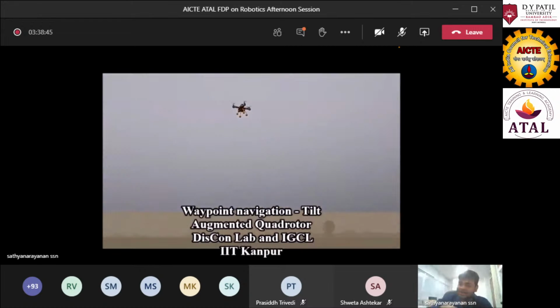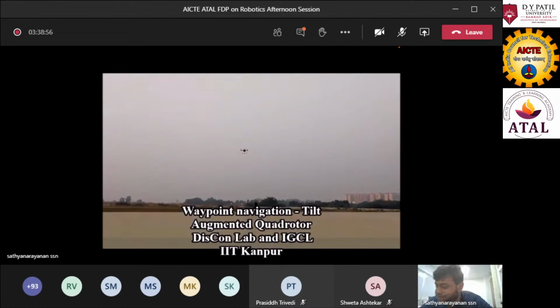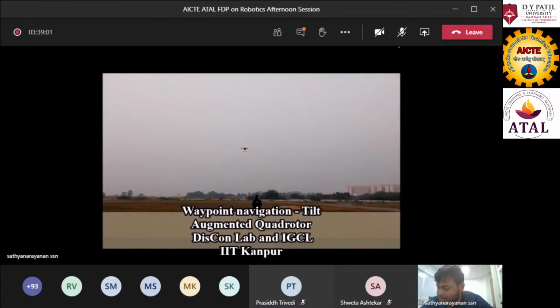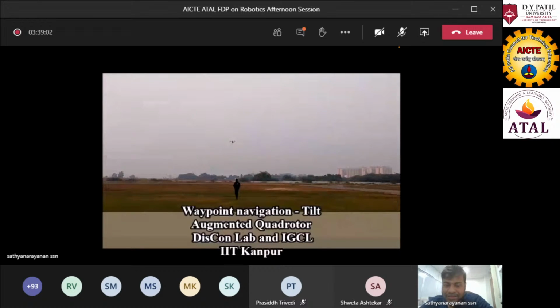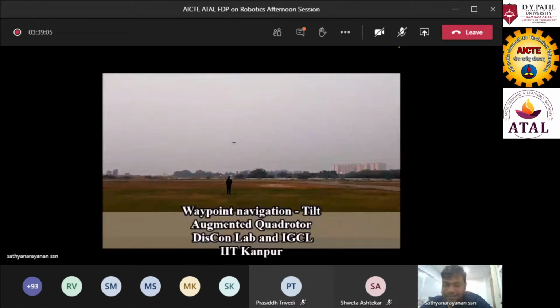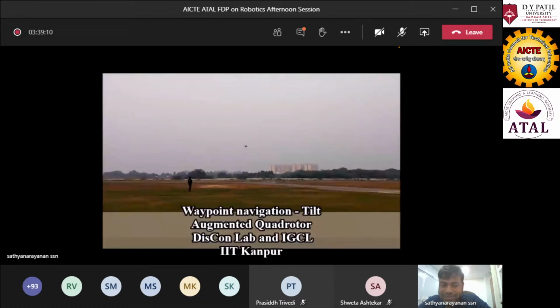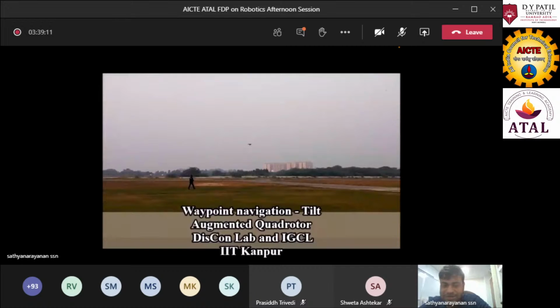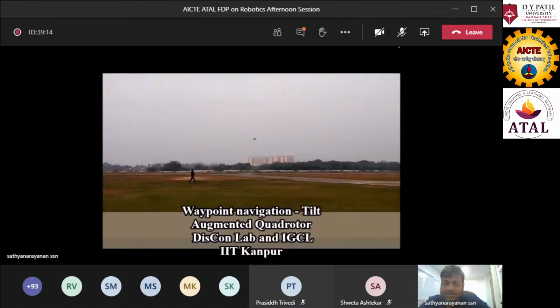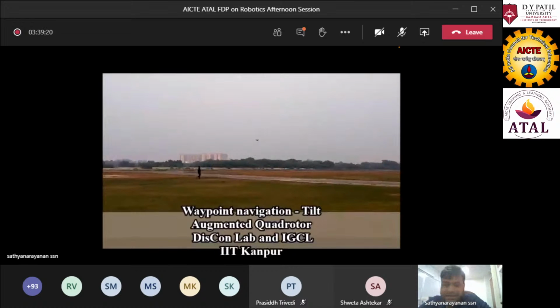In order to land vertically down when the vehicle is moving at very high speed, you have to maintain zero orientation. Then it is very useful. This experiment of landing on a high speed vehicle was done by the same PhD student. You can refer to his paper also. His control allocation does not minimize anything, but it is useful when you are just doing zero orientation and tracking the desired path.